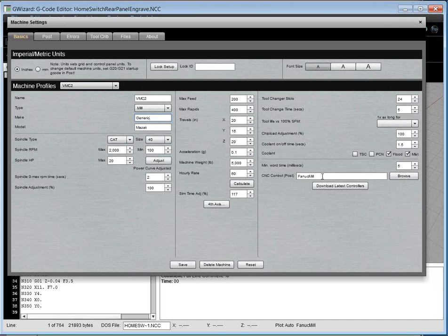And there are machines that claim they run ISO G-code, for example, and I've seen all kinds of differences between those machines. Even though there's an ISO standard, the machine itself kind of says, well, we're pretty close to ISO, so let's call this ISO. The RS standard in the U.S. is another one that's similar to ISO, and a lot of companies will claim their G-code runs that. The real story is there are a lot of different dialects of G-code, and you want to try to get close to that.